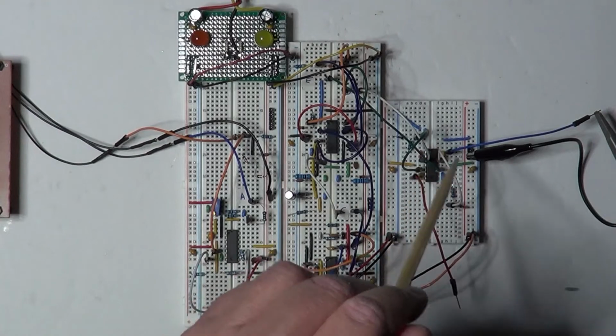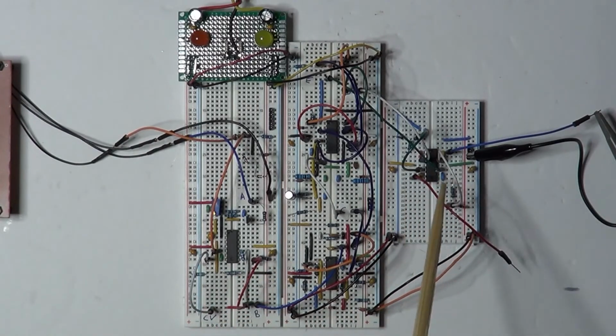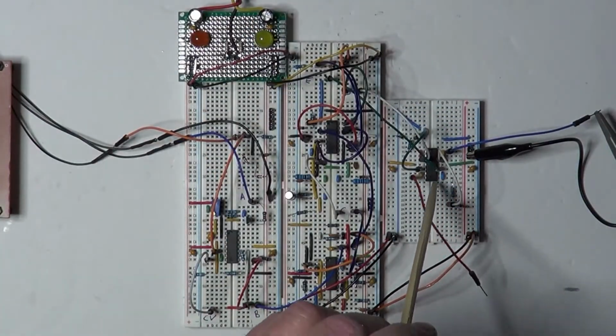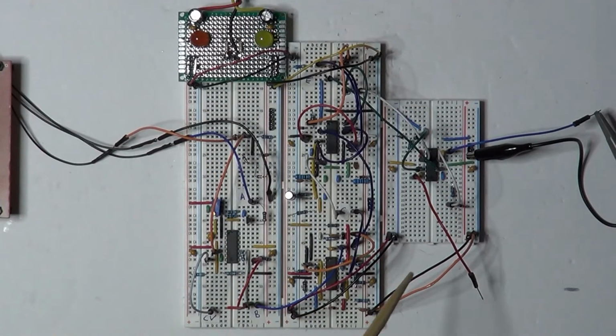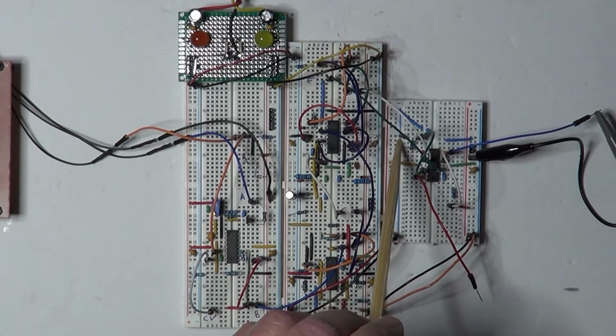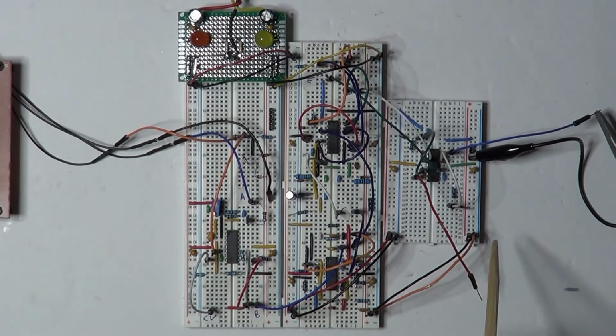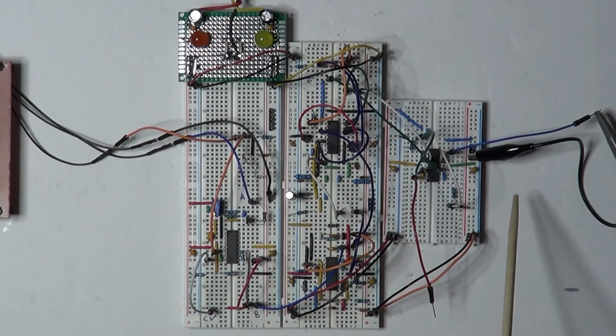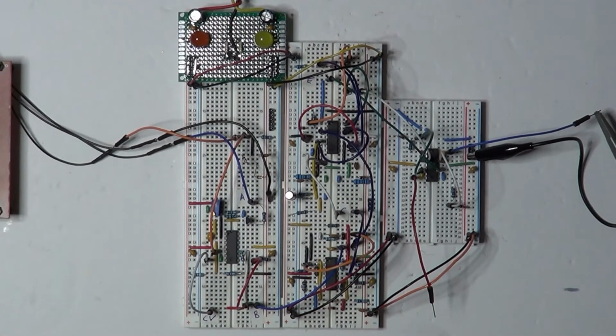This block here at the end is just the group of impedance adapters for both the trigger output and the gate. One is available on this cable and the other one is available on this other cable. And you can also notice the Zener diodes right here, one, and the other one is right here, which are used to cap the signal to the 5 volts necessary to make it work as a TTL signal.